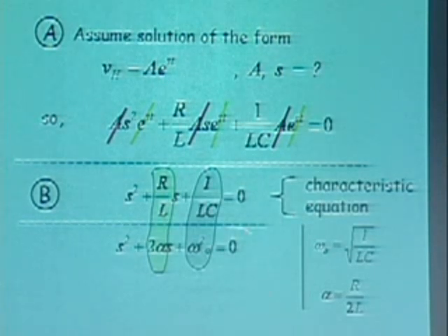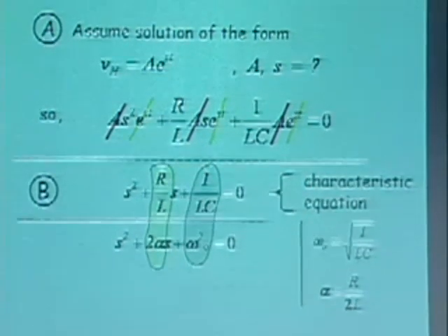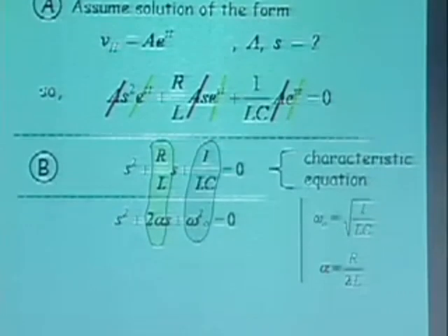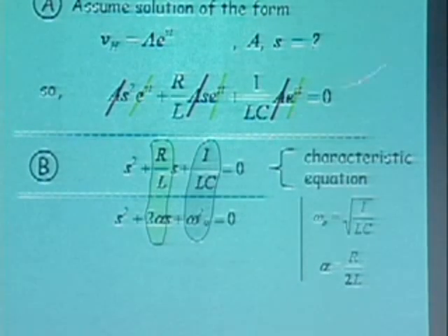Once I get to this characteristic equation, after that, I can give you one generic way of solving it. And depending on the kind of circuit you have, a series RLC, which is what we have, or a parallel RLC, you will simply get different coefficients for the alpha term. This is going to stay the same, but this term will look different. Alpha is going to look different. There's a real pattern here, and what I'm doing is simply focusing on what the differences are between the pattern you've learned in the LC situation and the RLC situation.